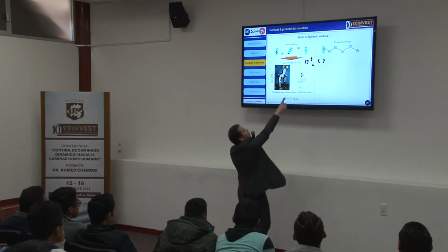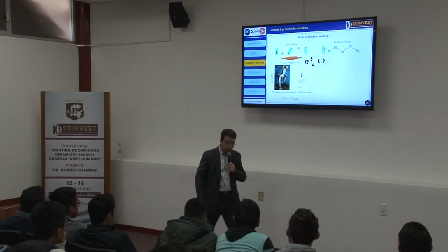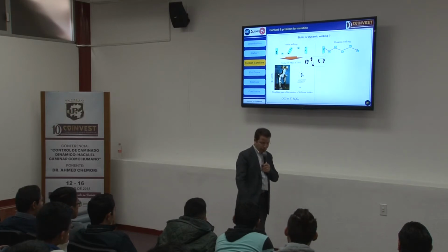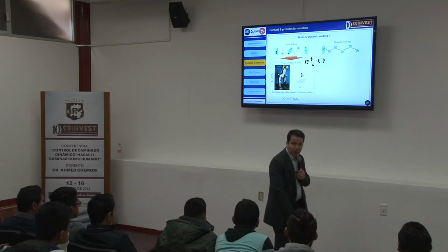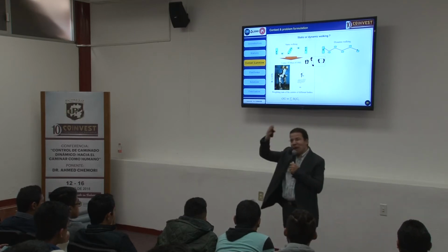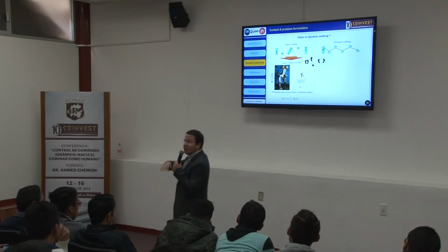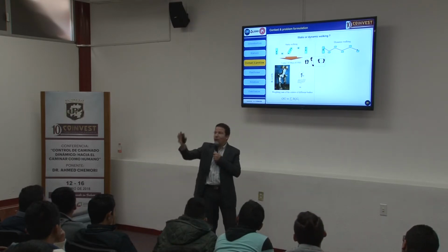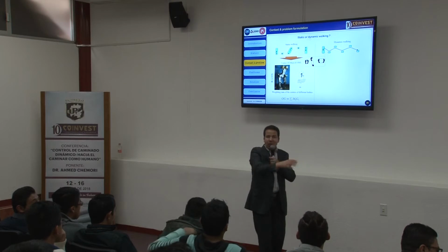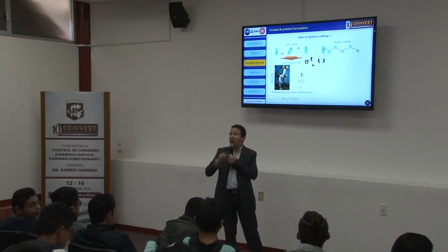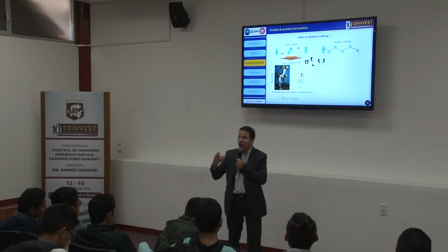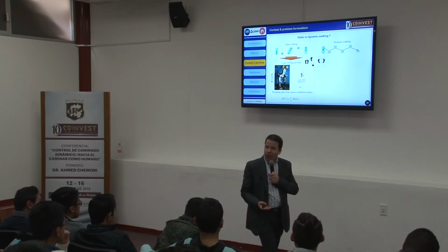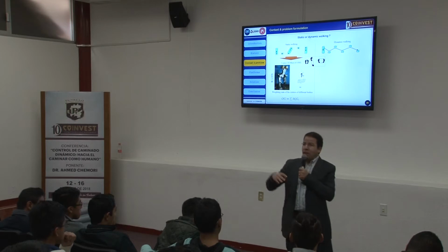Where is it inside? If the two legs are like that, for instance, the projection is inside. If I do this, it's outside, outside, outside, outside, up, inside, outside, outside, inside, and so on. So we have different phases, and alternatively, in a static way, we have stable, and stable, and stable. But if you look at the whole walking cycle, it's stable because the robot will not fall down. It's unstable. When it touches the ground, it becomes stable. And unstable, it becomes stable, and so on.